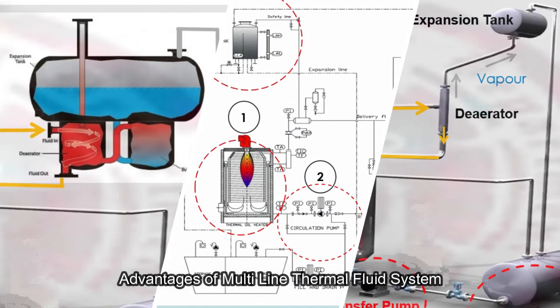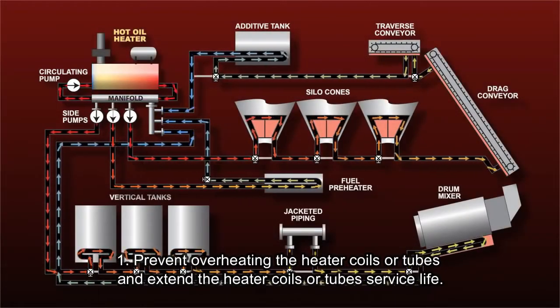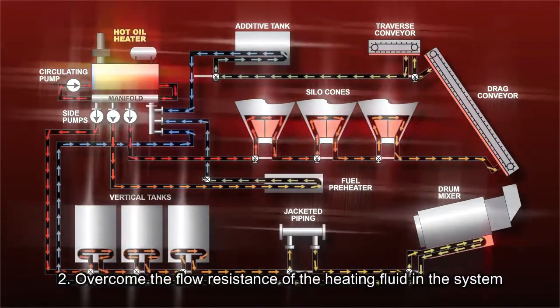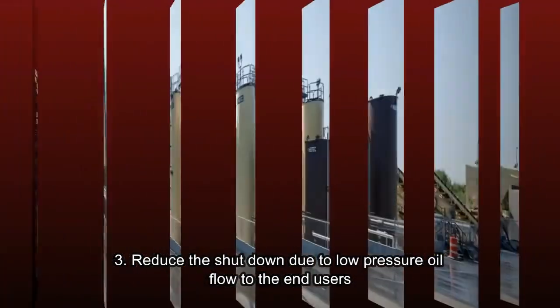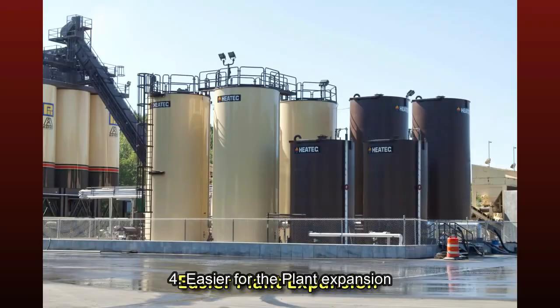Advantages of multi-line thermal fluid system. 1. Prevent overheating the heater coils or tubes, and extend the heater coils' or tubes' service life. 2. Overcome the flow resistance of the heating fluid in the system. 3. Reduce the shutdown due to low-pressure oil flow to the end users. 4. Easier for plant expansion.